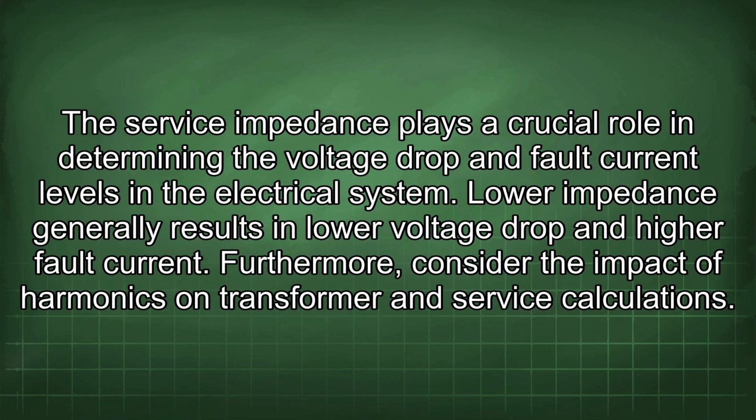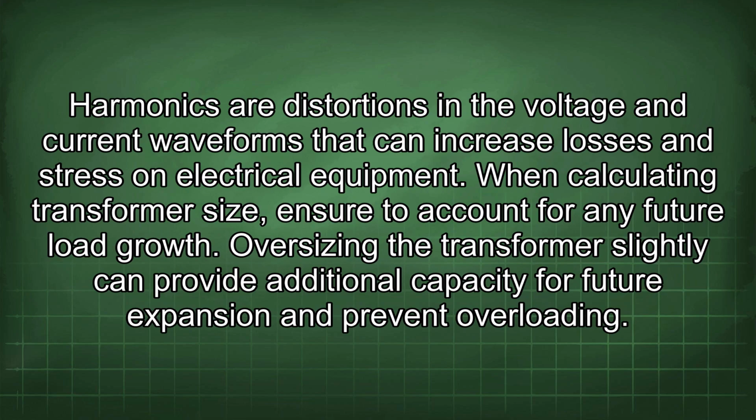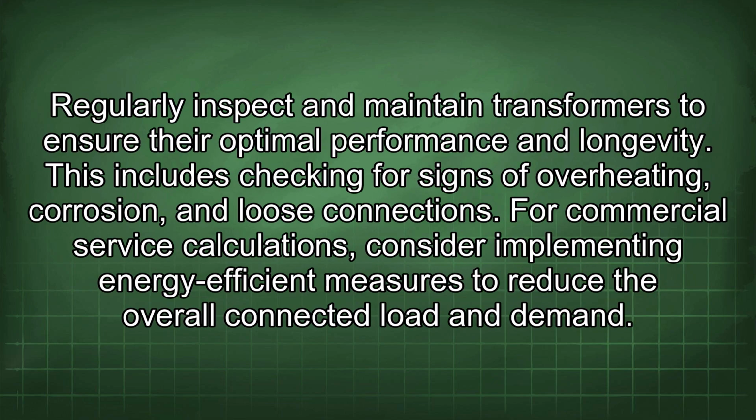Furthermore, consider the impact of harmonics on transformer and service calculations. Harmonics are distortions in the voltage and current waveforms that can increase losses and stress on electrical equipment. When calculating transformer size, ensure to account for any future load growth. Oversizing the transformer slightly can provide additional capacity for future expansion and prevent overloading. Regularly inspect and maintain transformers to ensure their optimal performance and longevity. This includes checking for signs of overheating, corrosion, and loose connections.